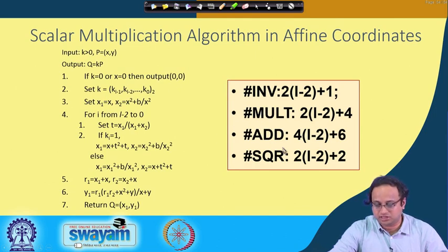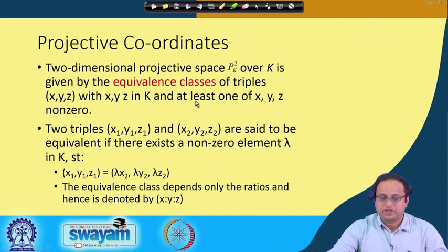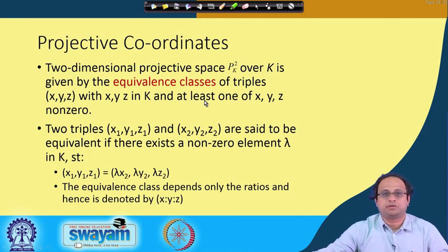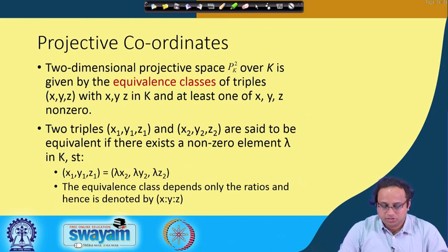And essentially what you would of course want is to reduce the number of computations, but in a plain vanilla format, this is the number of computations which you have to do. Okay. So now what the designers wanted to do is reduce the number of costly inversions, because inversions are pretty complex, and typically as a thumb rule, one inversion is equivalent to roughly 7, or at least more than 5, multiplications.